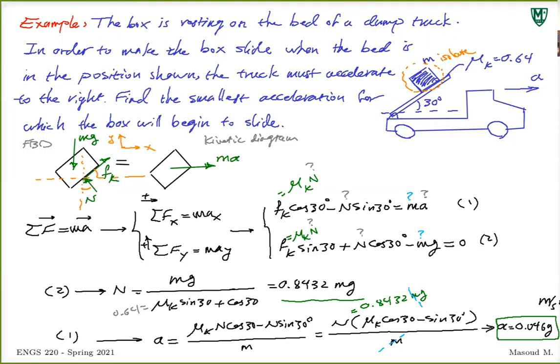Isolate that, draw the free body diagram, put all the forces, draw the kinetic diagram, right? Make sure all the components of acceleration are there, multiplied by mass. Obviously, you need to know inertial forces. The right side is referred to as inertial forces, because these forces are caused by the inertia, like mass or inertia. We'll talk about it later on when we get to rigid bodies. But write the equations.